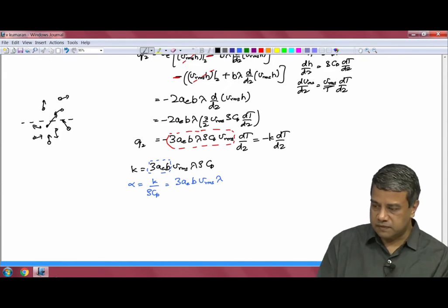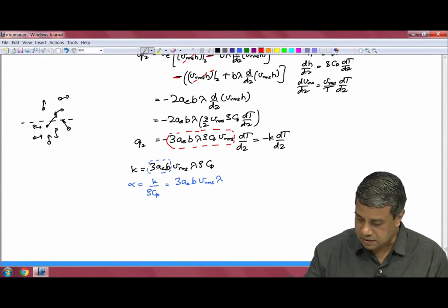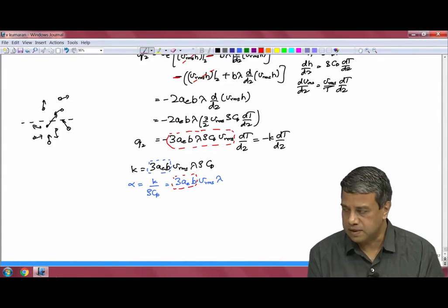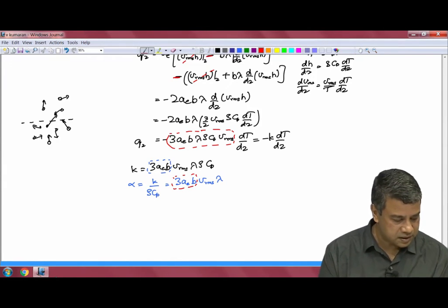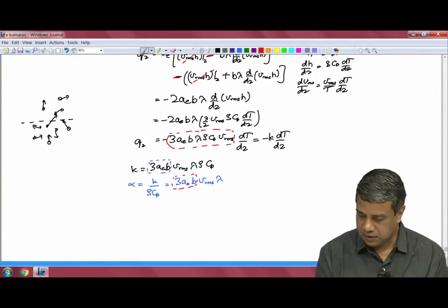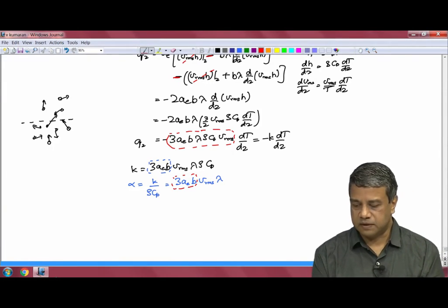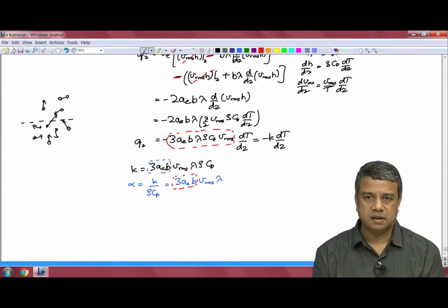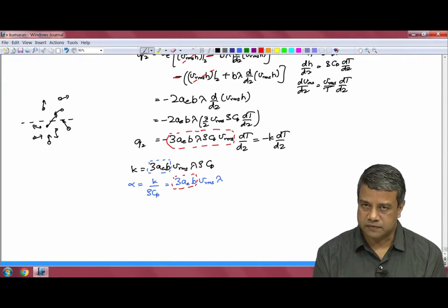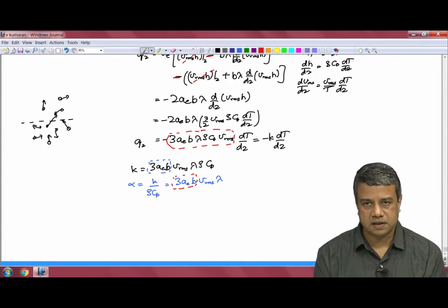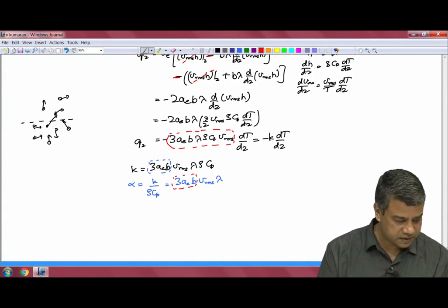The coefficient in front is different in general, but the dependence on the mean free path and the root mean square fluctuating velocity is exactly the same. So, to within a proportionality constant, we have got an expression for the thermal conductivity or the thermal diffusivity. In a gas, the diffusivities are all the same because the mechanism is the physical transport of molecules across the surface.